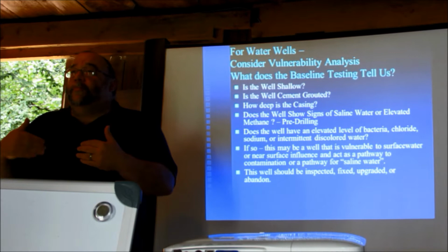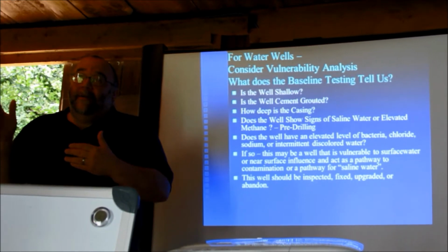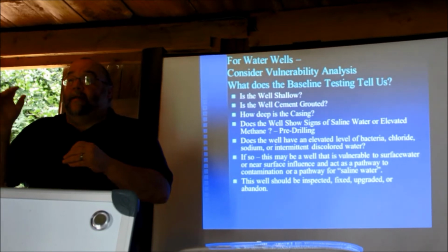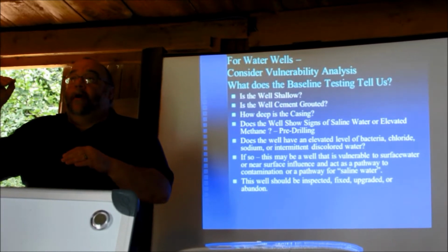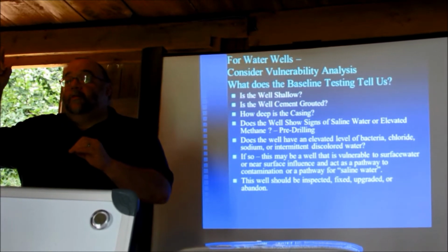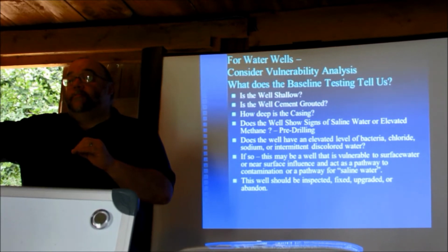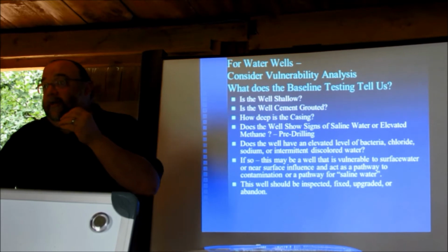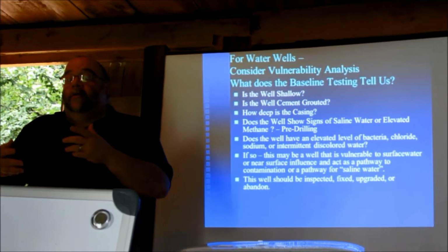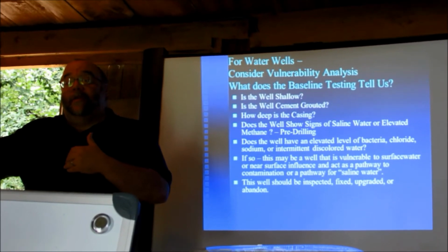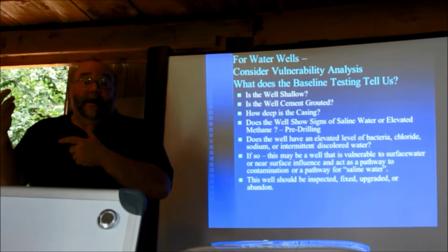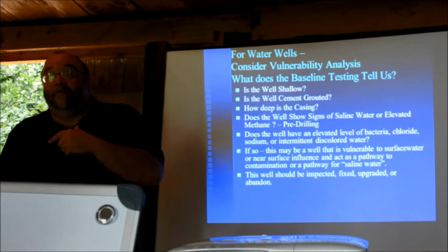So for example, off the top of my head, I think about a 250-foot well that has a static water level of 50 feet. At the surface, this methane level will be 28 milligrams per liter. At 250 feet, it's about 200. So if you get a water sample out of a well that's above 28 or 30, it's actually supersaturated with methane because it hasn't had the opportunity to outgas, because you're pulling it from 200 feet down.